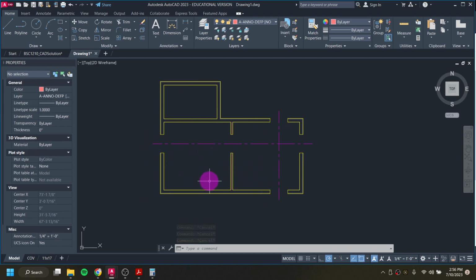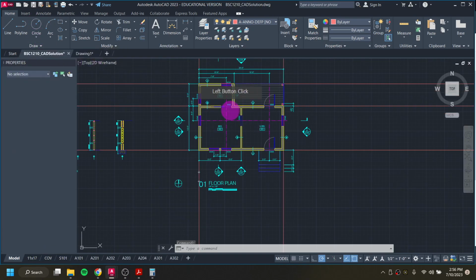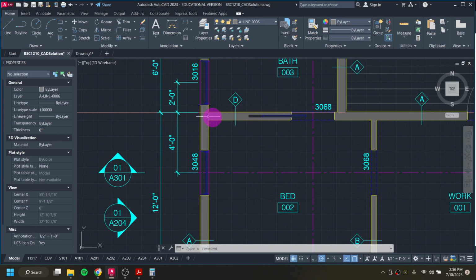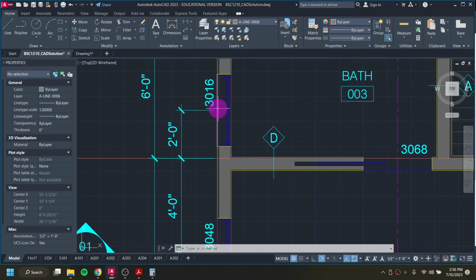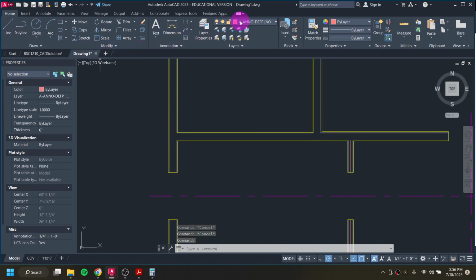Next up that I can do is my next kind of opening that I can do is I'll do this window next. Why not? So from the face of the plumbing wall, 2 foot up is where the center of this window sits. So I'll go back into my drawing here. And I'm still in the depth point layer. I'm going to draw a line.